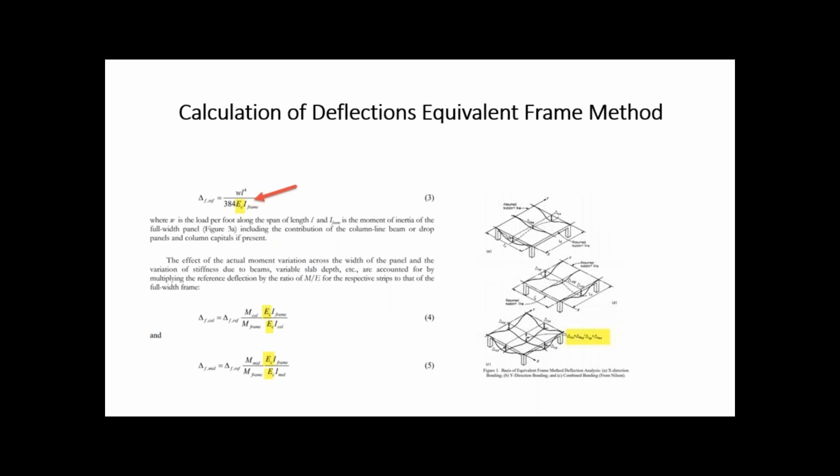Okay, for slab deflections, note the importance of f'c in the equation for slab deflection, at the red arrow. This is the normalized overall equation that you would use for a simple beam movement. Note that the modulus of elasticity is in the quotient, and obviously a variation of 10 or 20% would affect your net calculated deflections accordingly.